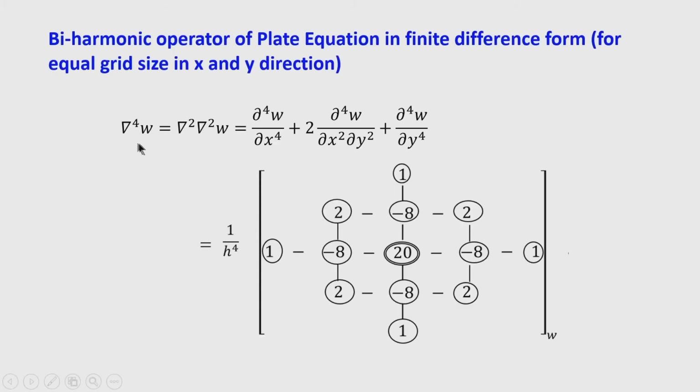So, we have got the fourth derivative. Now the fourth derivative in the x direction I have obtained, and the y direction can also be written just by aligning the stencil in the vertical direction. So, after arranging this you will get the fourth derivative, that is del 4 w, the biharmonic operator that is used with the deflection surface to form the plate equation.